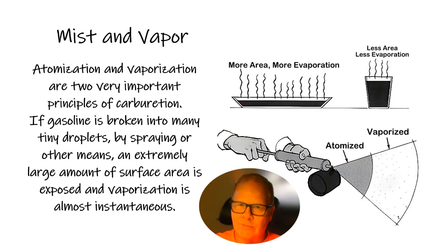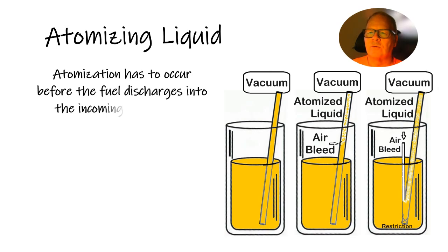They'd have a heat riser down there, and they want to warm that manifold up right under the carburetor so it's going to vaporize that fuel. That's called the EFE system, early fuel evaporation. We don't ever think about that, but that's what an exhaust crossover is about, where it's crossing over under the carburetor. Some of your old 390 Fords had a heater hose pipe running around the base of the carburetor for that same reason. So anyway, that's for whatever it's worth.